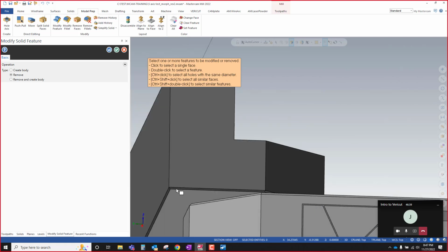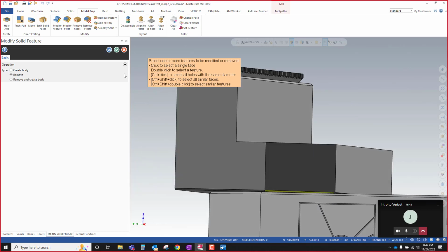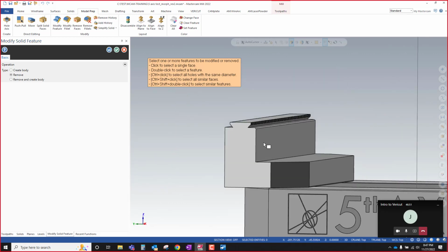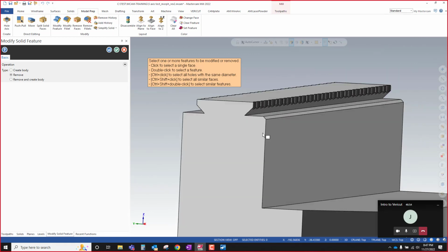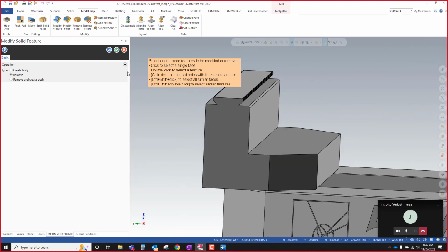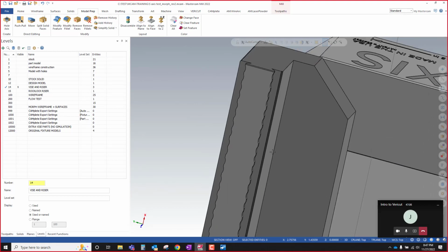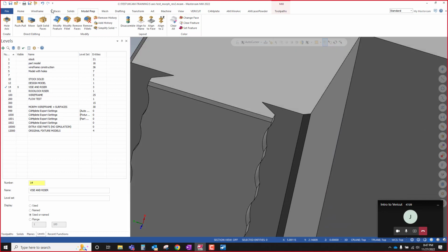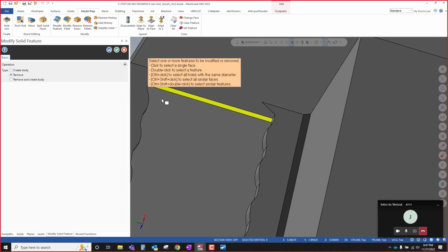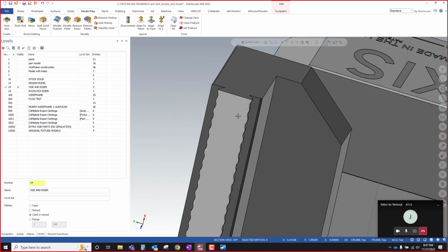let's certainly come over here. Oop, not that guy, this guy. Get this down to where it is one solid face. I can leave that chamfer in, that's not going to hurt anything. I'm going to save it. Save often when you're defeaturing a model, because you can get stuff screwed up pretty quick. I'll do modify feature remove on here, and that should be good.